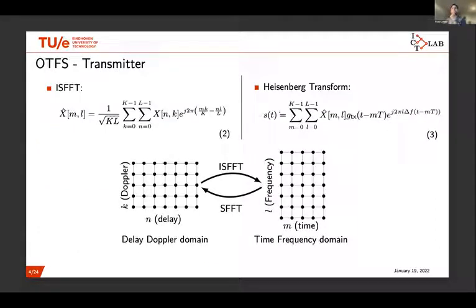So we have here, when we look at the inner sum, the subcarriers with subcarrier spacing delta F, which is typically chosen to be the inverse of the pulse length, capital D. And that's everything at the moment that I'm going to talk about OTFS. I will come back to this OTFS later, but let's continue and let's talk about some radars.